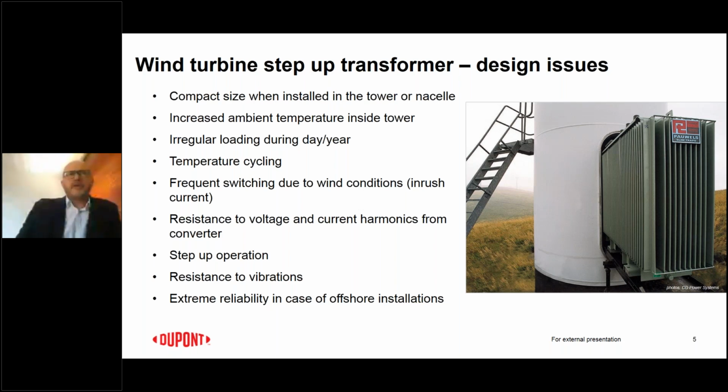Specific things related to the loading of the transformers: definitely the load of the wind turbine, and the transformer consequently, is depending on the wind conditions. So these transformers experienced very irregular loading periods during the year, depending on the wind conditions. Very specific cyclic loadings, irregular cyclic loadings, and temperature cycling. So the expansion of the tank was very periodic and irregular compared to the regular distribution transformer. So there were more and more things identified which are specific to that type of transformer.